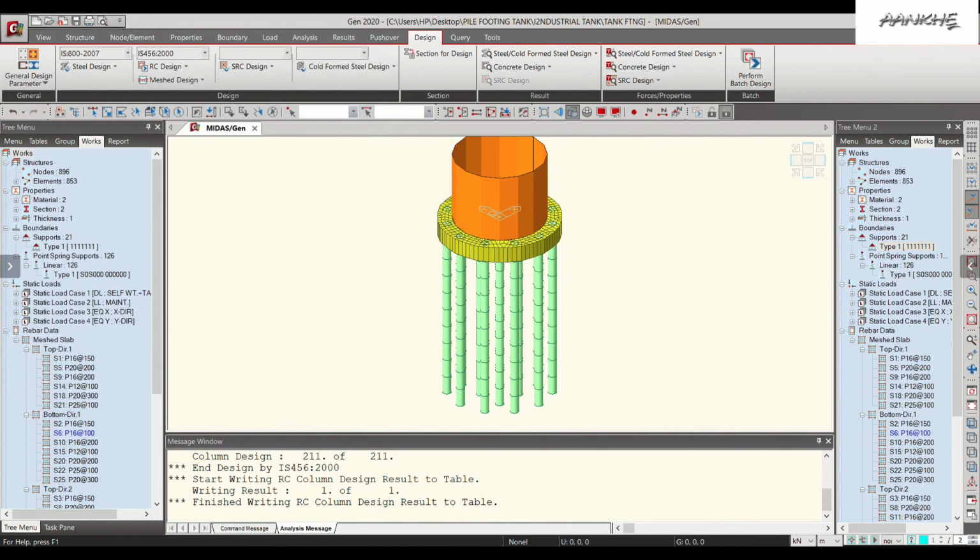This is just the possibility I explored, but in this project we did not take this into account because it was an industrial project, and generally what happens during construction, lots of faults are there, and since it is an acid tank, in due course of time, whether we admit or not, acid will be percolating, right? So it will also be hampering the life period of the concrete. So generally for industrial structures we go for a little bit heavier design with a little higher factor of safety or little higher margin in design. So I just explored the possibility of how to economize.